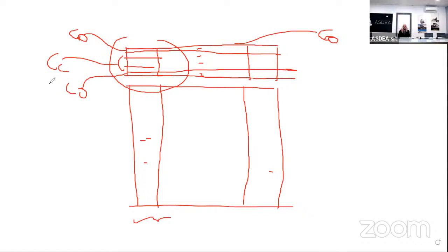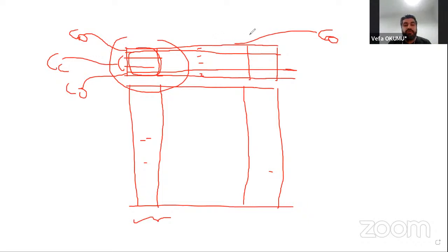Which is basically the same thing that you would do with a beam element, because otherwise there is no way to account automatically for confinement like you could do in 3 dimensions. Okay, I have to model the end-zone separately. Yeah. Okay. And the second question is, you know, SSI analysis takes too much time, and I want to